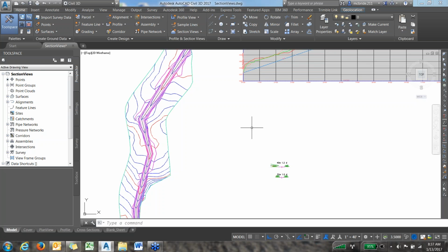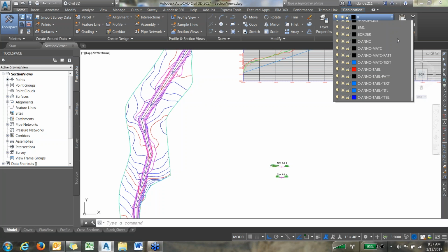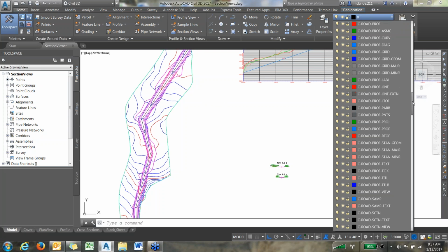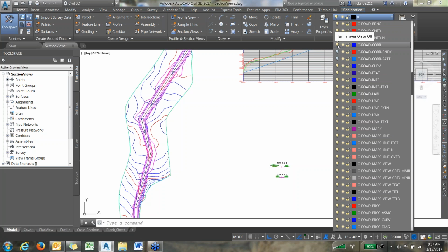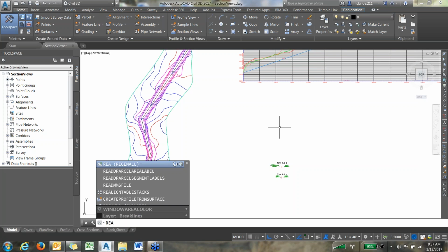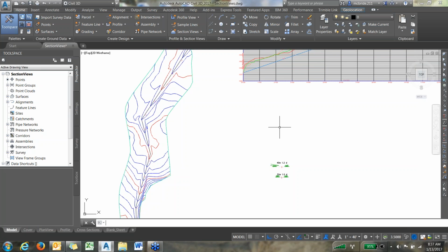There we go. My CAD was lagging behind. You should see now these purple lines that follow the alignment of the waterway. That's the corridor. But it's kind of confusing with all those lines on there. That's why I turn it off once I'm done with the corridor part of it. So I'll go back down to C-Road Core, and it was the top one. I'll turn it off. Again, I have to redraw my drawing to get those purple lines off. And there they go.